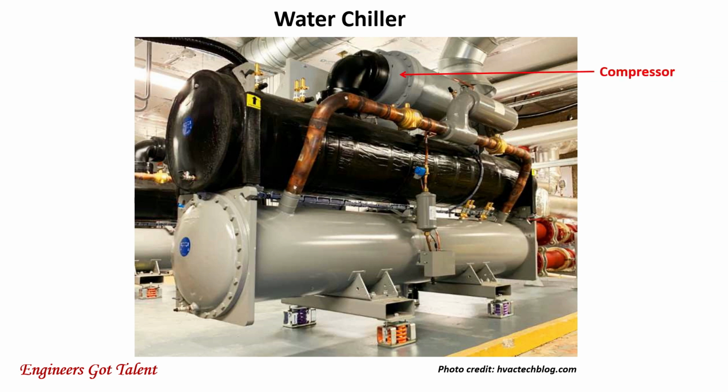This houses the compressor suction line, the compressor discharge line, the evaporator, which is insulated with black fiberglass with polyethylene foam underneath. The insulation preserves the temperature of the chilled water at 7 degrees Celsius inside the evaporator tubes. This is because it takes a lot of money to produce chilled water. The condenser is not insulated because this equipment is a heat rejector, which does not need an insulation.